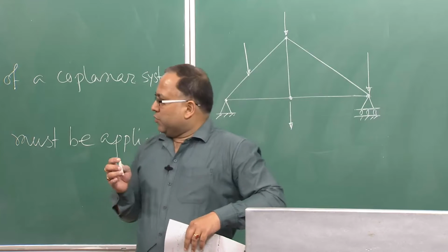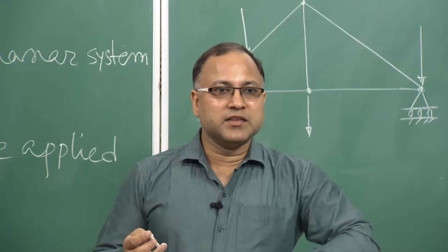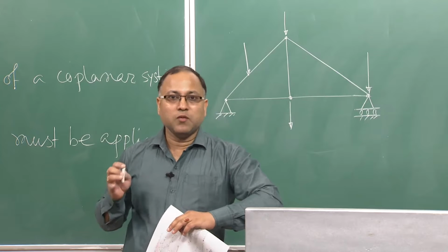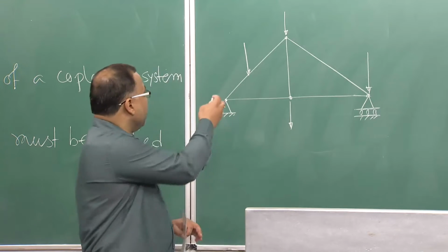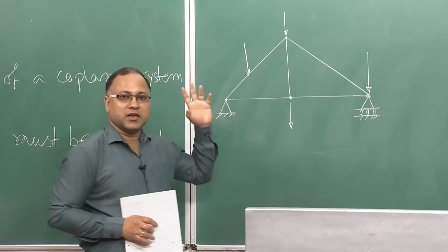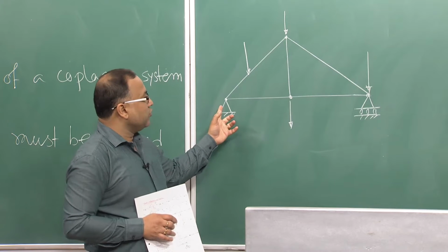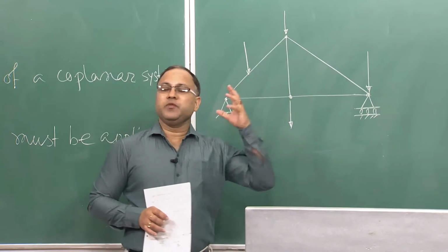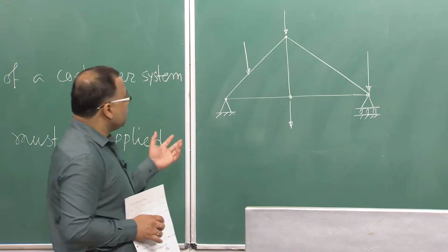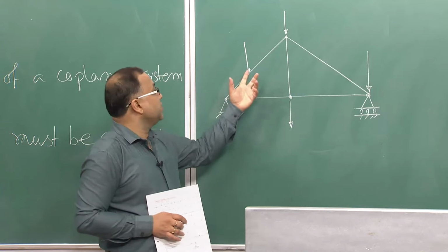Well, so I will stop here today. In the next class we will continue with this truss and see how to analyze it, and we will learn few methods by which you can solve the truss. Solve means finding the member forces. If you want to design a truss, first you should know the support reactions, which you will get by using your equations of equilibrium. Then once you know the support reactions, under the application of the external forces, what are the different member forces?